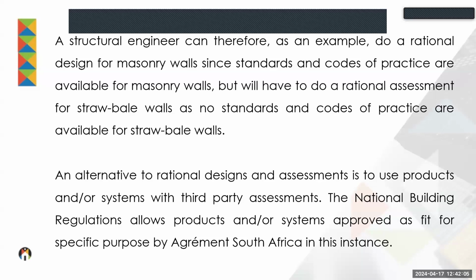But what about a straw bale wall? We have got no performance criteria or design standards or codes of practice for straw bale walls. So in that case, you must do it through testing. You might have to go and erect a test wall, do some tests as prescribed, for instance, in the regulation B, on those to determine failure points. And if those failure points are above a certain limit, he can then say, I've assessed that this wall will withstand all these forces that can work into it, and therefore I say that it is okay.